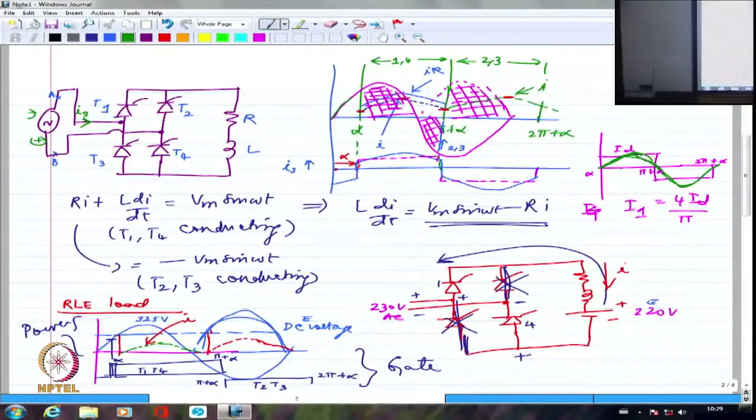So that is actually going to play a vital role in deciding what kind of power factor I can anticipate in my circuit. Because this is essentially pushing the current behind. That angle is telling you how much the fundamental current is being pushed behind.